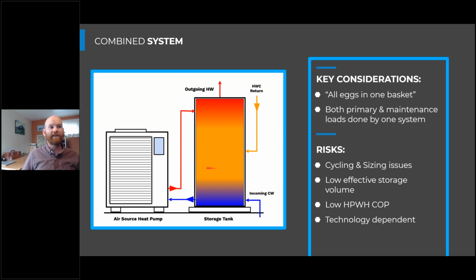So we have to be aware of that when sizing, because if we're sizing for our primary load, which is 3 times larger than this, and we're sizing for the design day condition where it's coldest outside and it's the coldest water that we're heating up, we might have a very oversized heat pump to treat this return water.